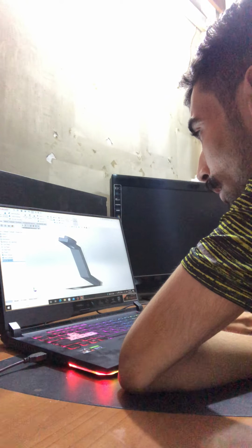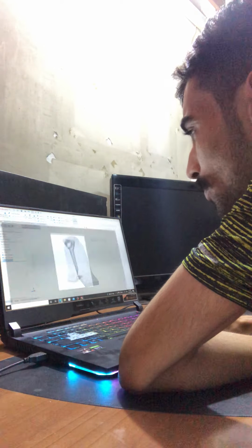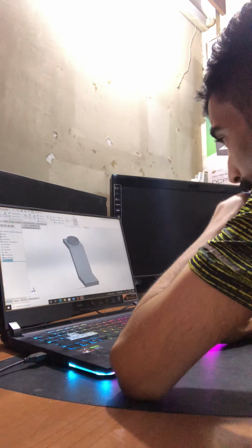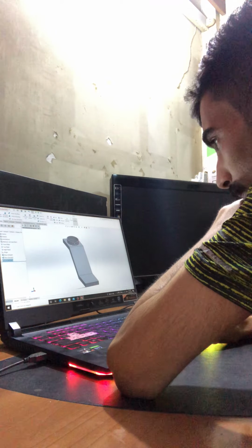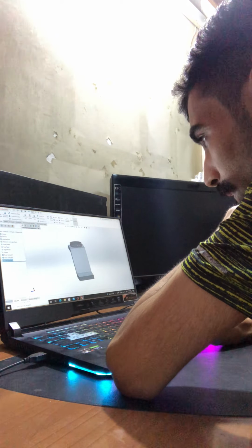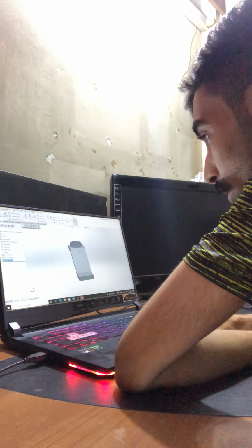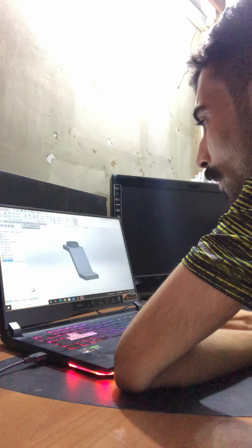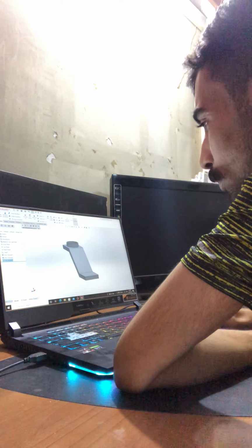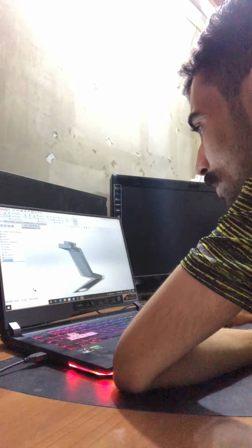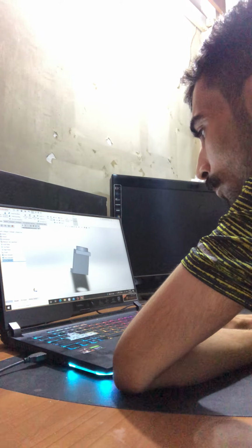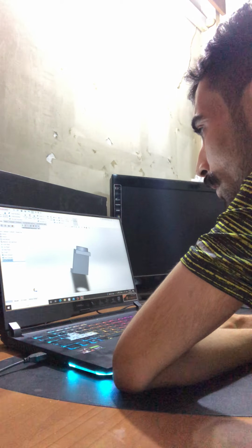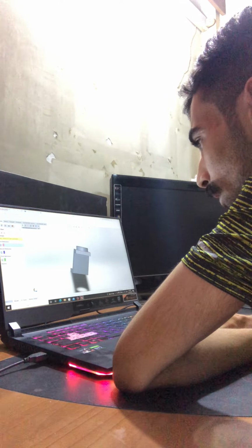So after that, we have a small circles at the both direction. If I draw the circle from this point of view, our direction will be wrong, because when we choose the extruded boss or cut extruded, our orientation will be wrong. That will go to the another plane. So I need to select the first plane that I will work for, and I'll choose from the feature reference geometry and plane and select this plane.